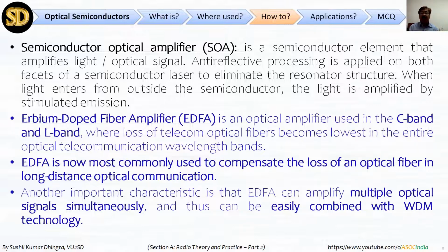This optical amplifier is used in the C band and L band, very high frequency, where the loss of telecom optical fiber becomes lowest in the entire optical telecommunication wavelength band. And this EDFA is now most commonly used to compensate the loss of optical fiber in long distance optical communication.